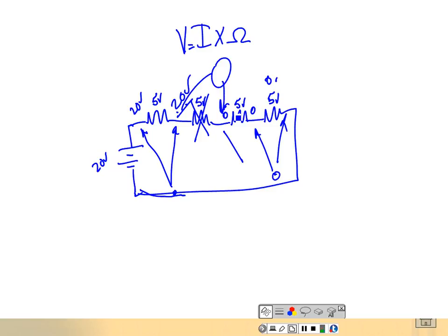Well, you've got to have watts, right? So to get watts, you've got to have V times I. It's just that the wattage is very low. So yes, fuses will drop a voltage, but very, very little. I might have a fuse that's rated at 600 amps, and it might drop 2 volts, but it's going to be running on a 600 volt supply, right? So if a fuse drops 2 volts, I'm still getting 598 volts to my load. There's not going to be enough of a difference to cause any problems. So fuses will drop some voltage. Switches don't drop hardly anything if it's a good switch.